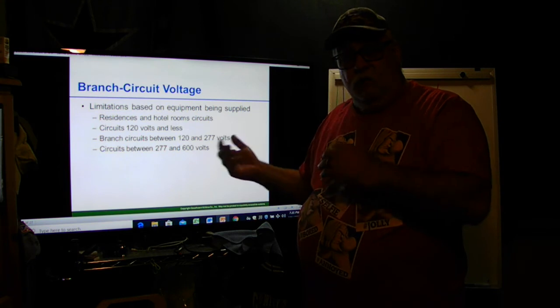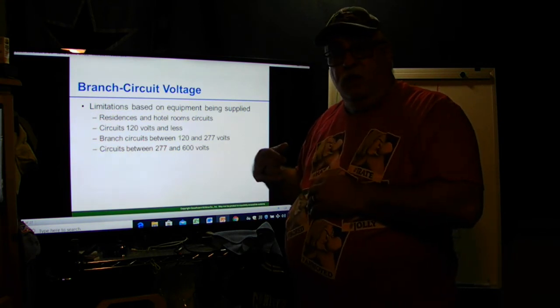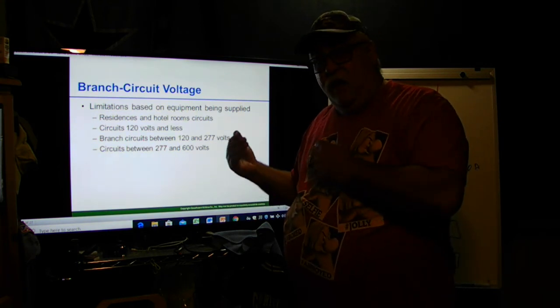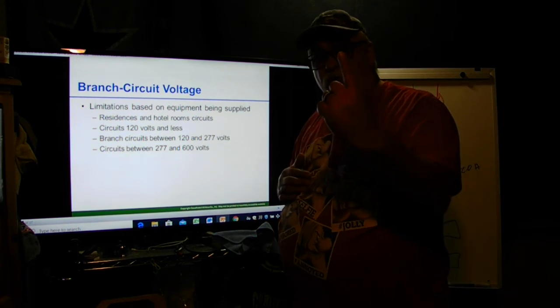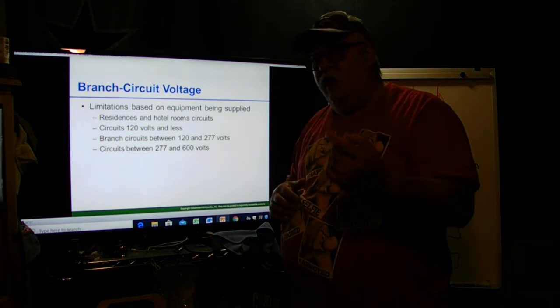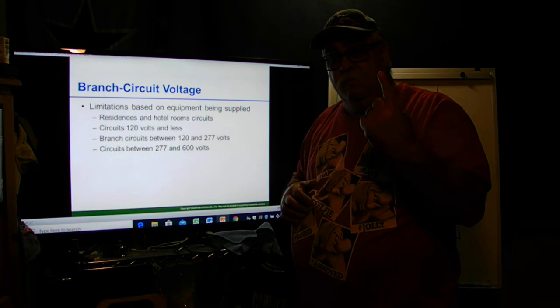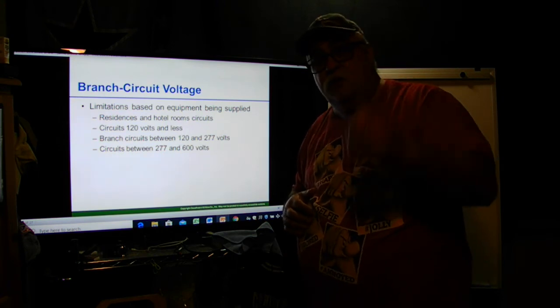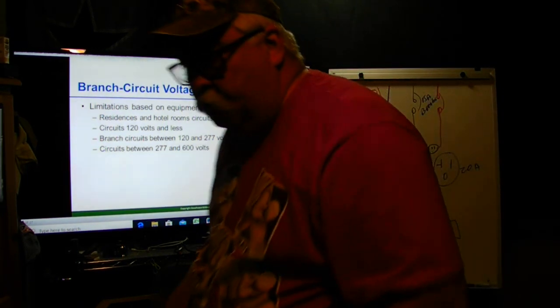Okay, now turn around and do that at 480. And I got 1 amp. Now I can have 16 lights on one circuit, maybe 17 lights on one circuit. Okay, so that's less wire that I got to run, less breakers that I have to use.